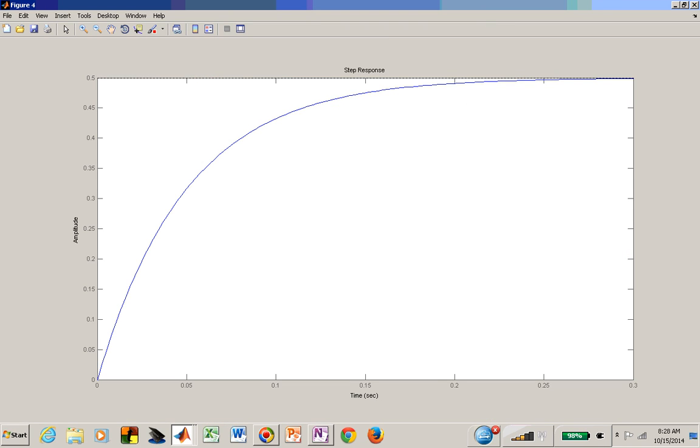There is now the step response. And what does that look like? Does that seem consistent with what we were expecting? Now we just have to pay attention to where this trajectory is actually moving to. It's moving to 1/2. And where did we command it to move to? 1. It was a unit step. So we have an error of 1/2. Our steady state error is 1/2.